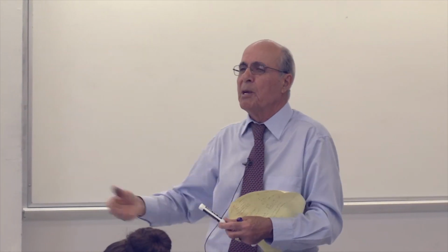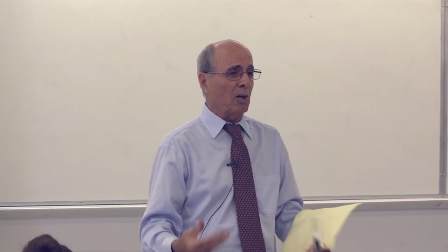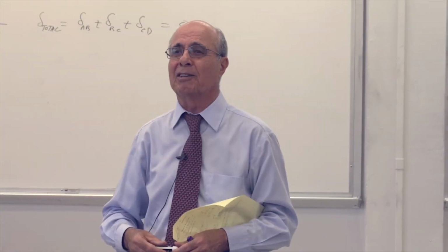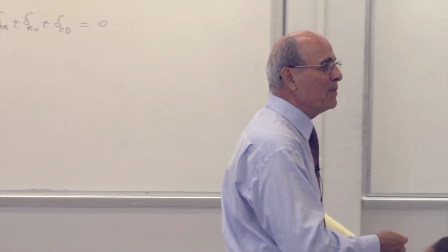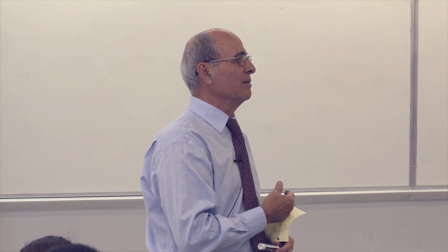Everybody see what I'm talking about? We are doing the same thing. But as soon as you see RA, if I put 10 here, everybody says 10. I put RA here, everybody looks at it. But what's the difference? RA is a force not yet determined. Is that correct or not? The force in member AB will be equal to RA in tension. Agreed or not? Yes.